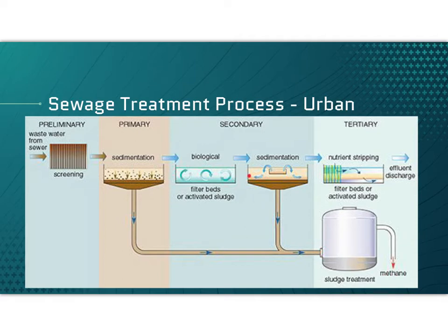We're also treating with chlorine and UV light at this point. In tertiary, we are stripping the nutrients that are not good for our water supply in filtering beds or some sort of filtration device, whether that is a lagoon or a marsh or maybe a man-made thing, to try and remove phosphates and nitrates and then releasing that water back.